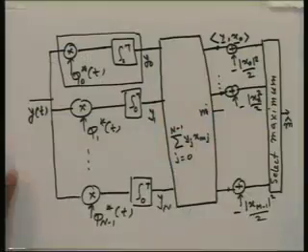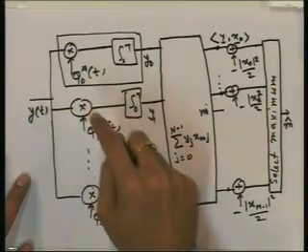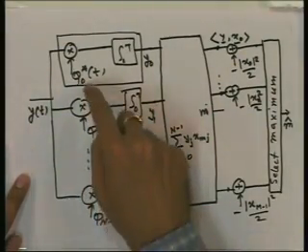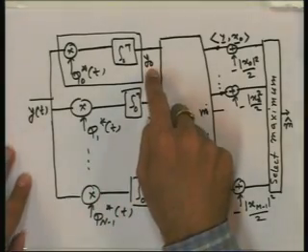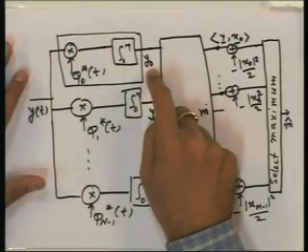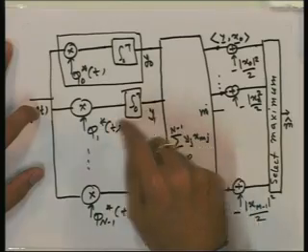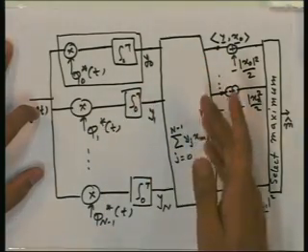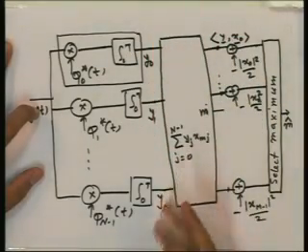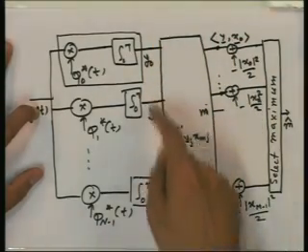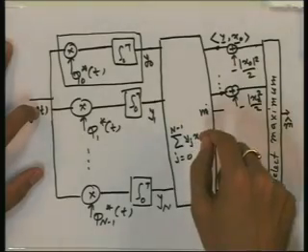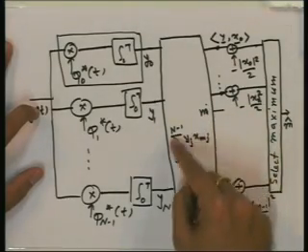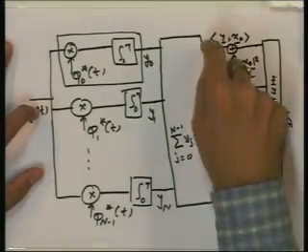We have seen how to demodulate for the signal set, using this block diagram by computing correlation, first by multiplying by the basis signals and then integrating, we can find the correlation of the received signal with the basis signals, and then find the correlation of this vector with different signal vectors x m by performing this operation for each m.